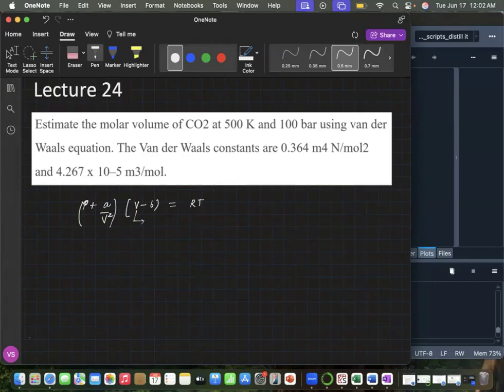So that implies if we want to use fsolve over here and we set it up as a problem for a non-linear algebraic equation, we are going to write this in the form of f(V) equals 0, right? That means towards the RHS, we must have just 0.